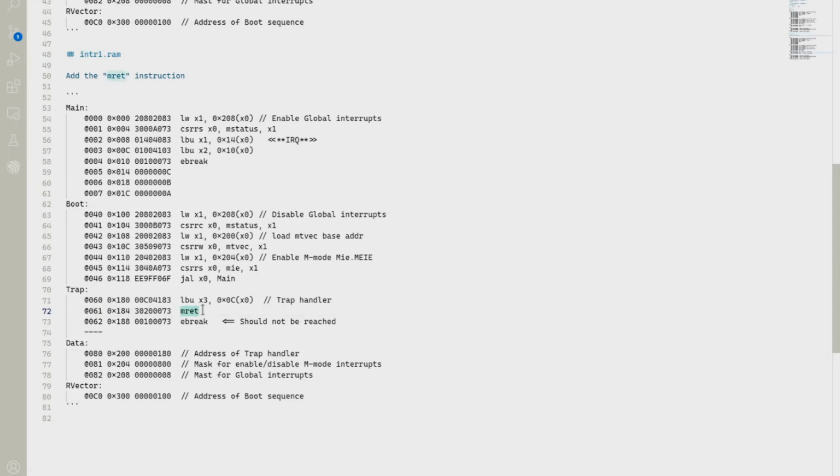Here is the mreturn instruction that we're going to test. And the way we test that is by forcing an interrupt to occur. That interrupt is this little signal right here. This is where I've set up the loop code in C++ to interrupt this instruction while it's executing. Now, the way the specification says is that the instruction must complete first. So even though the interrupt occurs during the execution, it's in between the lines here during the prefetch stage that it will recognize the interrupt and jump.